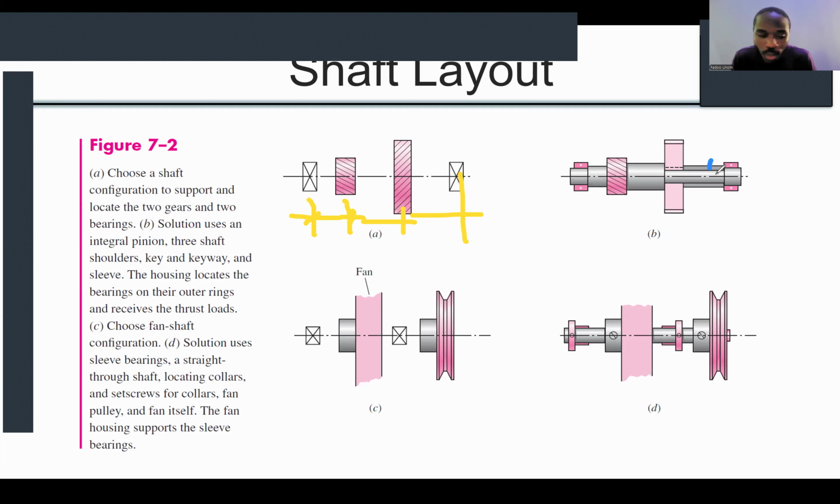That one there. So what it does is, now this is the main shaft. The main shaft is quite small. So when we fit the gear in and it has a key, we now use the collar to also provide support at the other end so that the gear is not free to move along the length of your shaft. It can't move axially. It can just stay there. Okay. So we'll have that step.